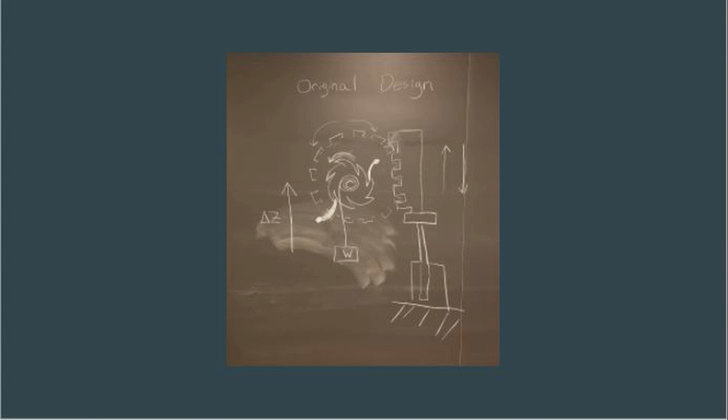A weight on a string is attached to the ratchet so that as the piston moves up and down, the string is wound up in only one direction and the weight moves up. As the piston moves up, thus turning the pinion counterclockwise, the ratchet turns in one direction. As the piston moves down, the pinion starts to turn clockwise, but the ratchet is caught by the pawls and locks until the piston starts moving up again.